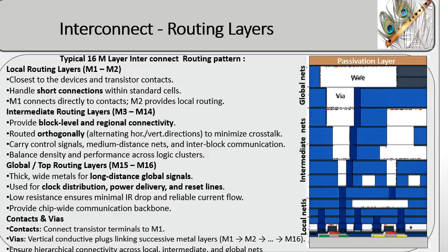The overlapping metal layers are isolated by dielectrics yet vertically integrated to optimize routing density and area. This isolation, however, introduces parasitics that limit speed and dissipate power. To minimize these effects, adjacent layers are routed in orthogonal directions, reducing coupling and cross-talk. Vias connect the different vertical layers, while metal pins of cells and pads enable net connectivity. Ultimately, interconnect parasitics directly impact the power efficiency and performance of the die, making their optimization critical in chip design.